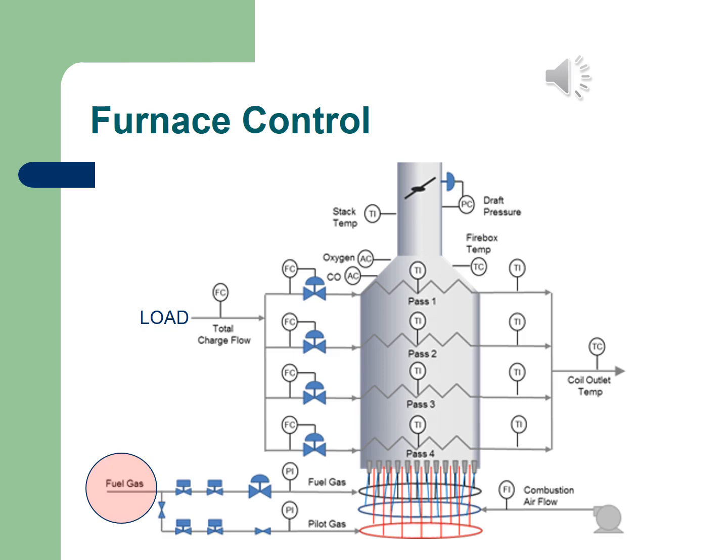Okay, so if you go to the fuel gas, you can see that the pressure of this gas section is controlled. What's important here is there are two parts, a pilot gas and a fuel gas. The pilot gas will usually be on, at a low pressure, and the fuel gas is the gas that supplies the main heat to the furnace itself. Pilot gas will usually be on first, and then you can ignite and have the rest of the gas flowing, and this can be controlled by a valve.